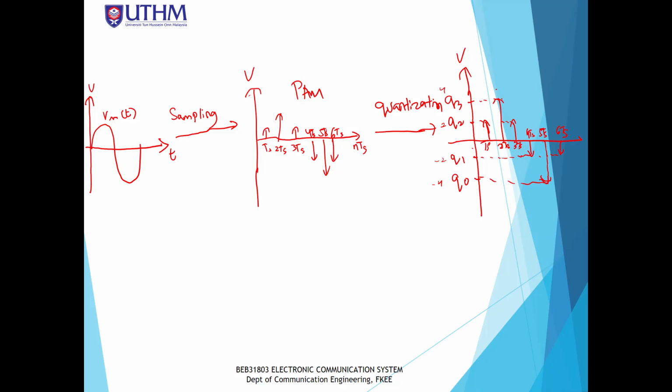So what you can see from here, I am rounding up the sample value to the nearest quantized level. So imagine I have 6 different values of sample. I rounded up to 4 nearest quantized levels in my example. Which is easier for me to do the signal processing if I only refer to 4 levels, rather than 6 or more different values.